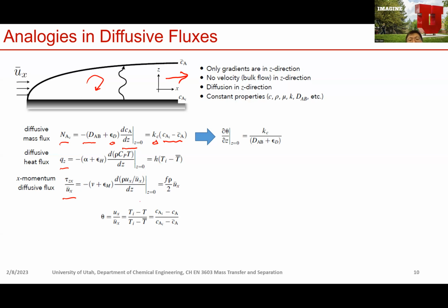These similarities are further evidenced if we use dimensionless concentration, dimensionless temperature, and dimensionless velocity. If you define such dimensionless quantities and plug them back into these equations, we find that the mass transfer coefficient, heat transfer coefficient, and the Fanning friction coefficient are related by this equation.